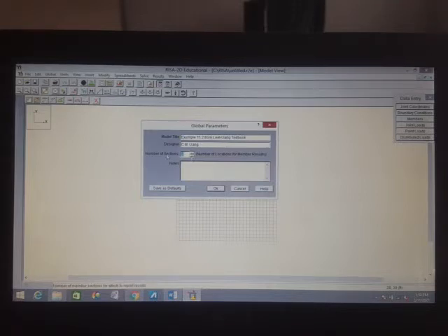Basically, the number of sections matters for, for example, a truss member having internal axial loads. Although the internal axial load is uniform all throughout the length, even if you select just two sections, that's going to be fine. But for flexural members, like beams, since the shear and bending moment diagrams differ at each section along the length, you might want to increase the number of sections.